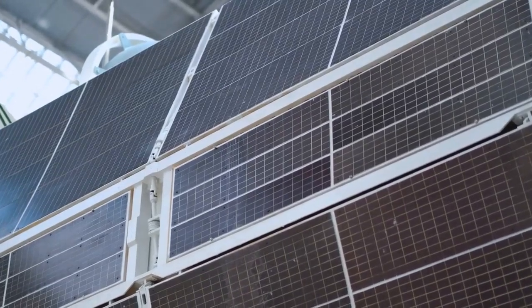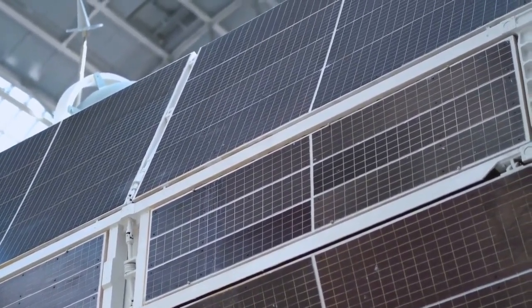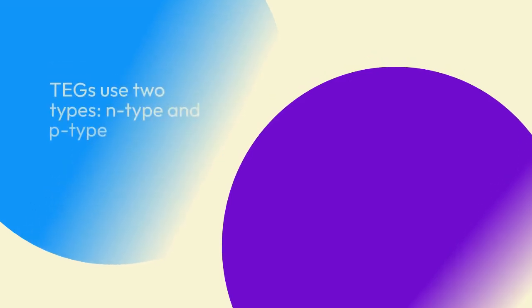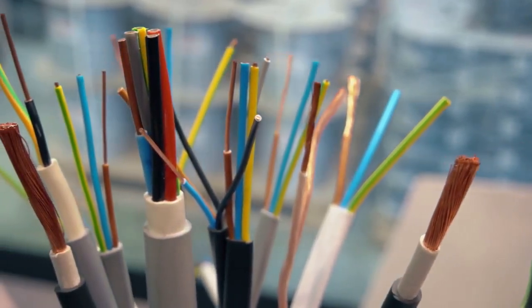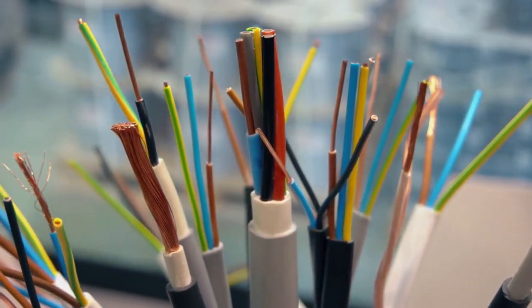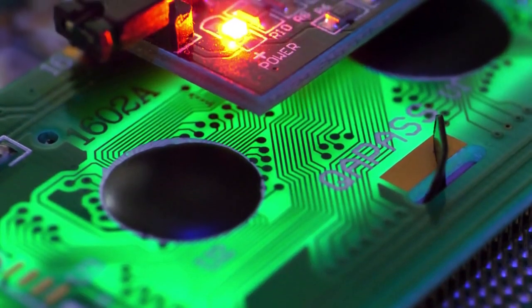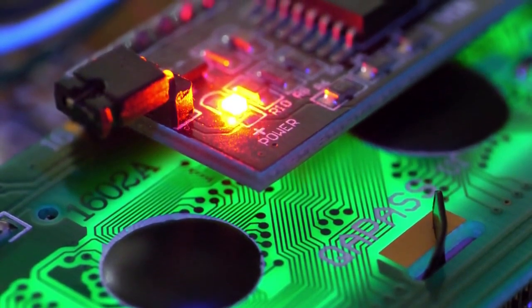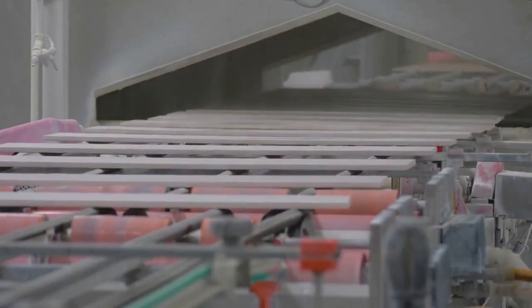However, a single material doesn't produce much voltage, so to build a useful generator, we need a more clever design using special materials. This is where semiconductors come in. TEGs use two types, N-type and P-type. N-type semiconductors have an excess of electrons, negative charges, while P-type semiconductors have a deficit of electrons, which we call holes, positive charges. In a TEG module, tiny pillars of N-type and P-type material are arranged side by side and connected with small metal plates, forming a series circuit. This entire array is then sandwiched between two ceramic plates.